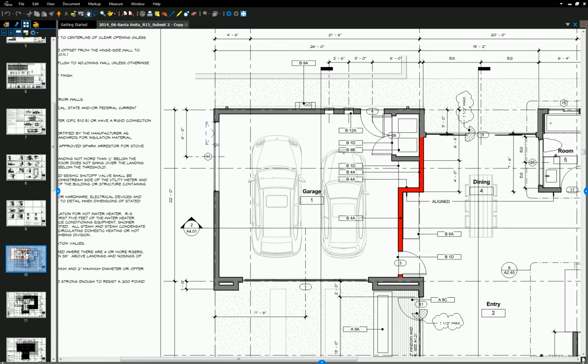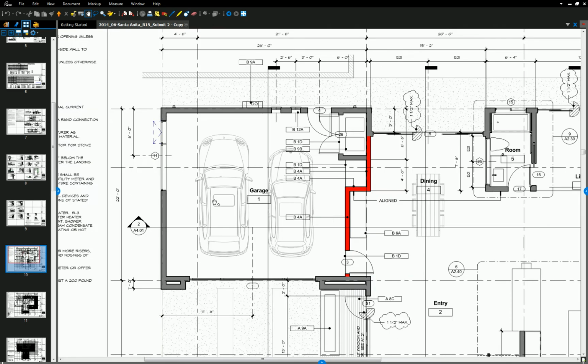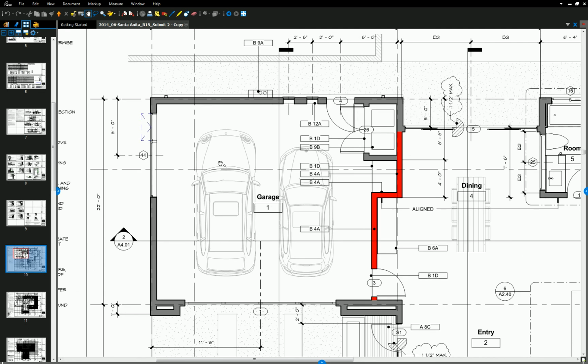All right, so with this being a schematic plan, we're using generic walls. And once you get your first couple grids in place, you guys can make the choice. Do I want to do just a couple grids and then add more on later? That's fine. Or you could go across the whole top of the plan and just do all the grids. Might be a little laborious, but it's there for you if you want to. It's your choice to be efficient. But I just started with this segment for now.